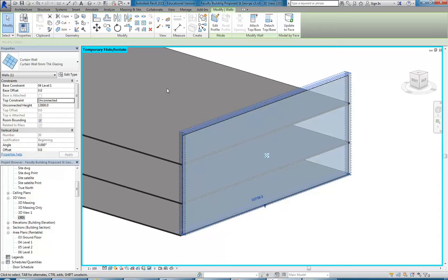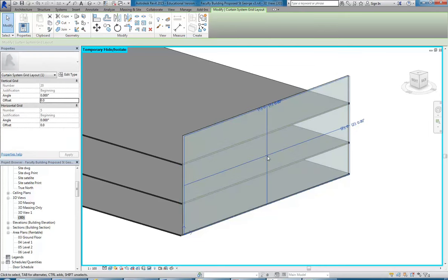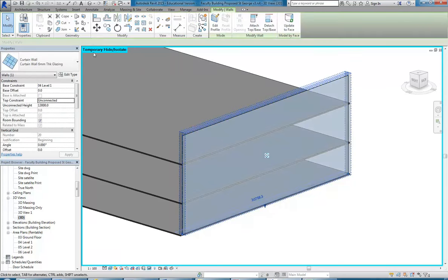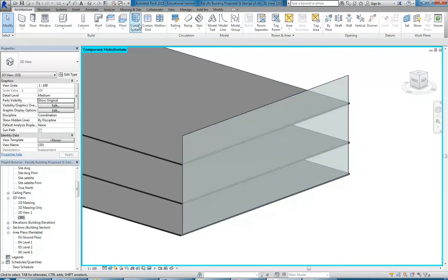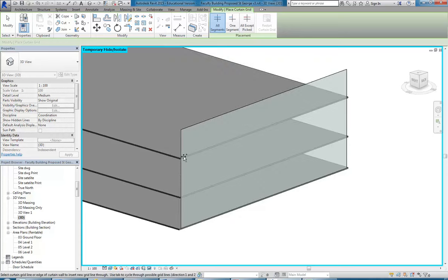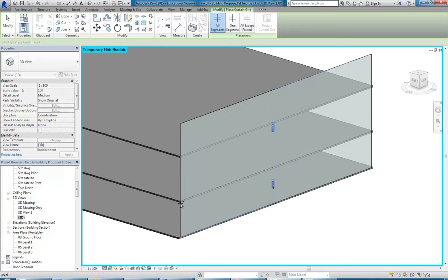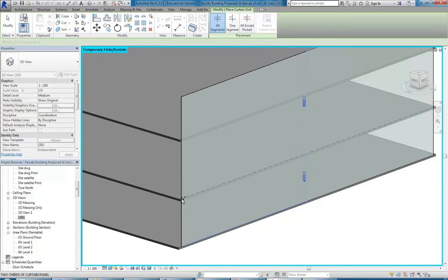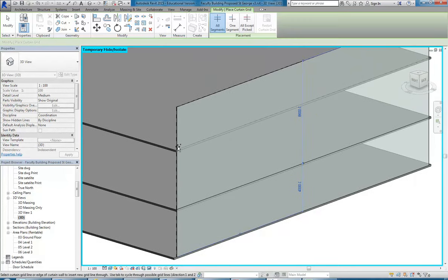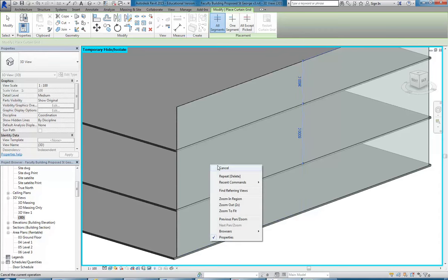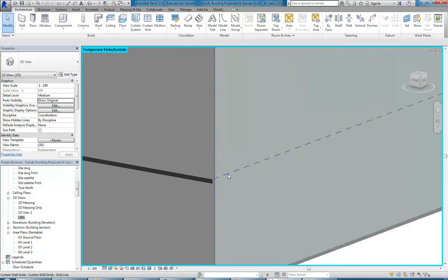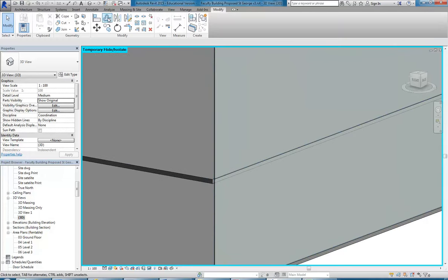So, again, actually, no, I'm just going to, here as well, you can click on that configure grid layout as well, and that gives you a few other options. Yep, so with the normal grid tool UI, you can't do angled grids, so here though I can just pick those lines and they probably will snap to my floors, but if they don't, you can always just use the align tool.